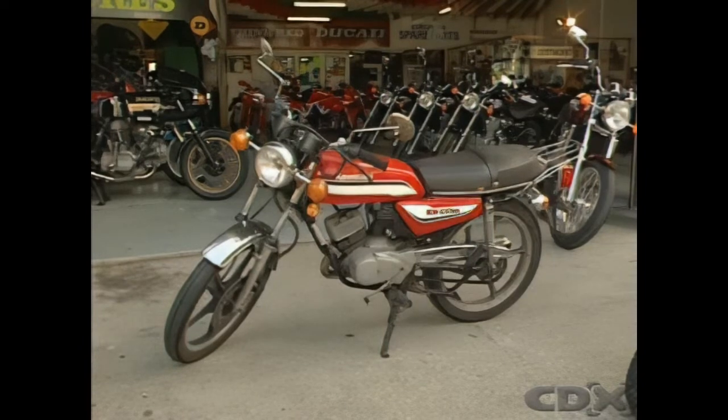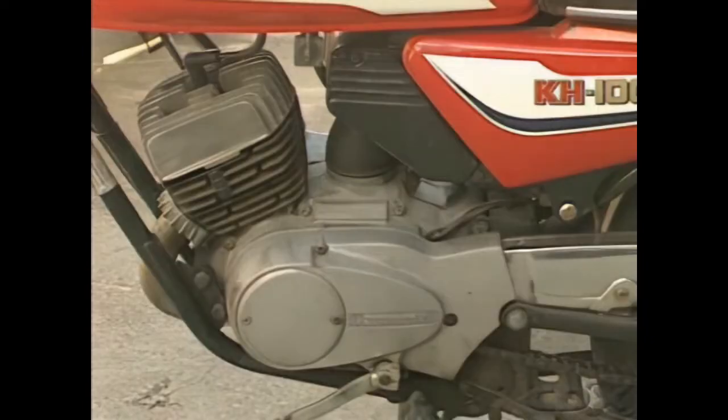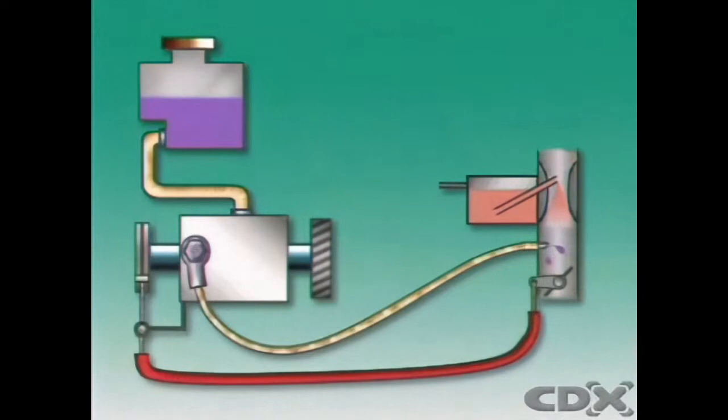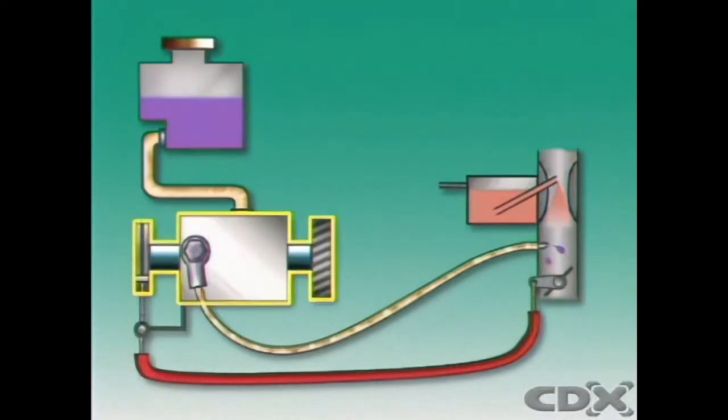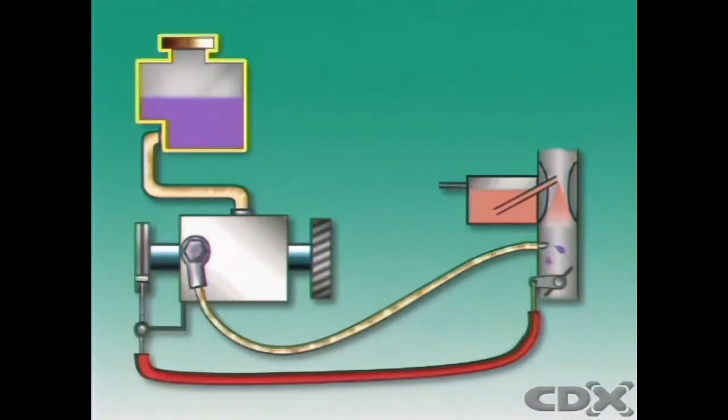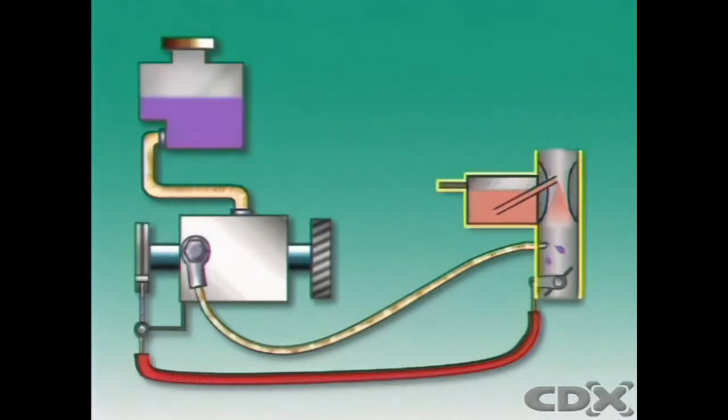Some two-stroke gasoline engines use an oil injection system. This system doesn't need the oil and gasoline mixed manually. An engine-driven oil pump takes oil from a tank and pumps a measured amount directly into the engine, where it will mix with the fuel and lubricate the internal engine parts. The pump delivers the correct amount of oil for the engine speed and the throttle setting, which makes it a more precise system than running the engine on a fixed oil-gasoline mixture.